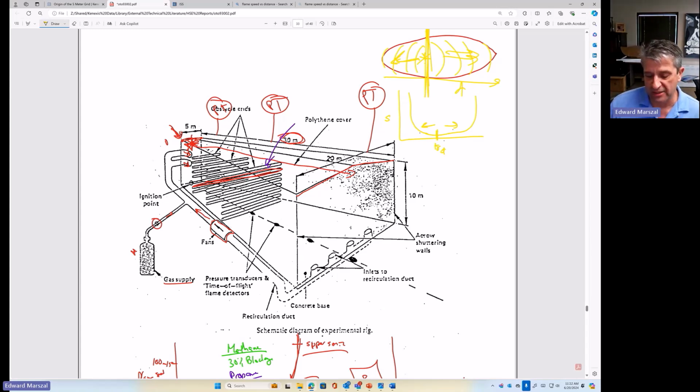And we want to make sure in our geographic coverage that if you exceed the size of a gas cloud that can cause harm, we want to be able to detect it. So if you wanted to do an analogy to toxic gas, you would say, what size of toxic gas cloud is capable of causing harm?